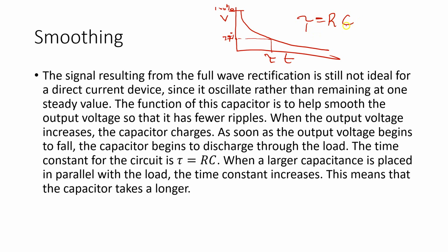The RC value is very important because, depending on the size of the capacitor, if you have a much larger capacitor, what it tells us is that the time constant is going to be much longer, which means that it's going to take a much longer time to discharge. You understand?